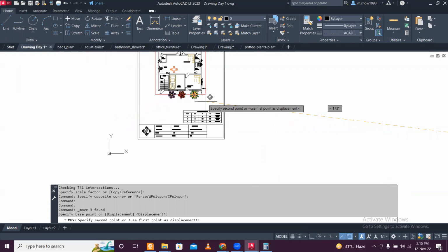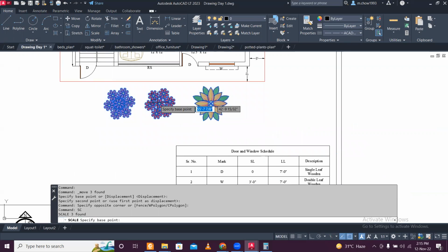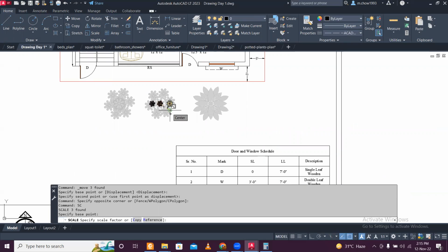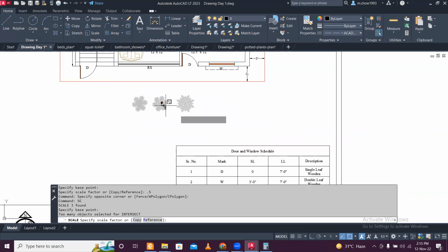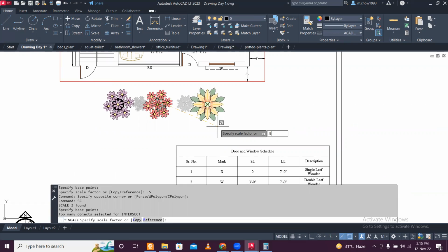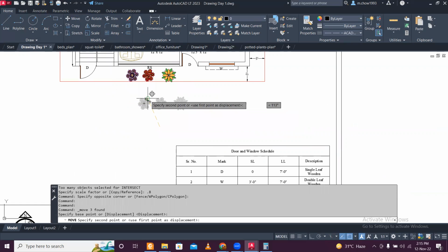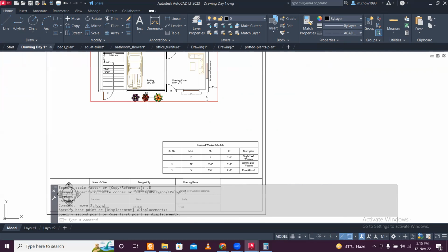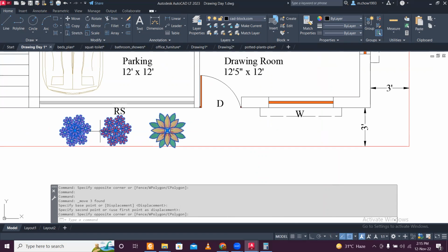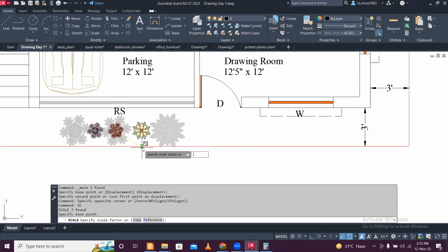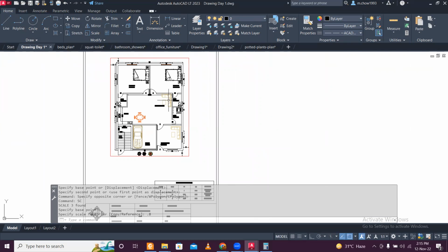The ortho is turned off. So we need to scale a little bit further. SC enter, take the central point of this, and let's do 2.5. Okay. And again, SC enter again. I'll just select this. I'll do 0.8. That's good. And I'll just move it. And in here, it denotes the garden in the front. Also, maybe scale it down a little bit, 0.8 again. That's better. So this denotes the flower garden in front, and these things.